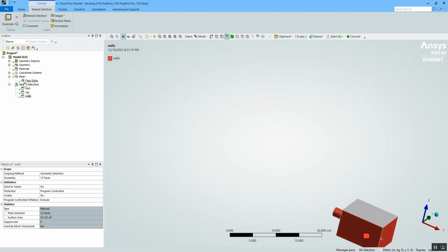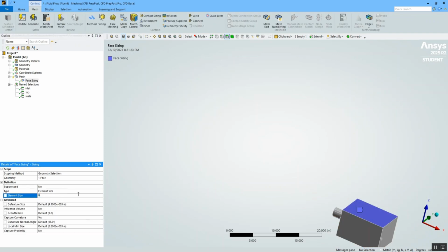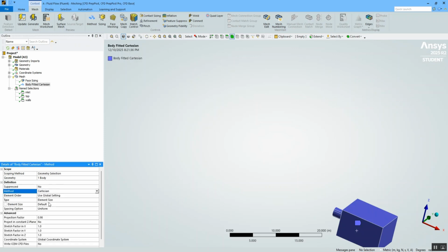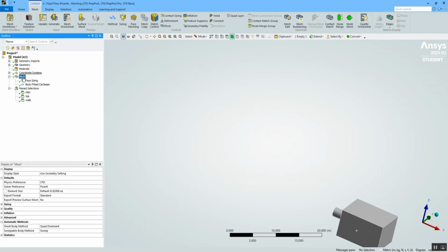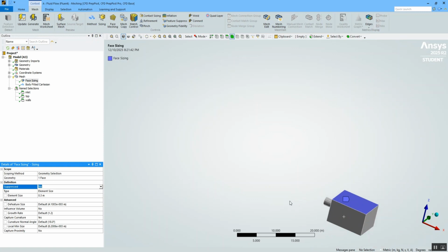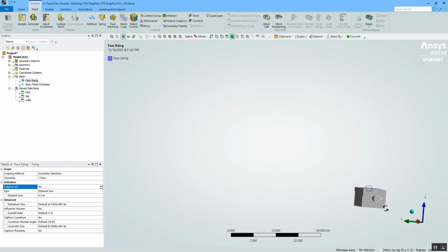Let's start our meshing. We will select a Cartesian type for simplification. Okay, there we select our method, and we choose a mesh size of 0.3 meter. I changed the geometry of the walls. You can change the geometry if you follow the first video and change it as you like.